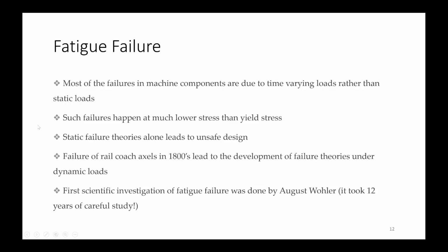Such failures happen at much lower stress than yield stress. So these can be below UTS and even below yield stress, depending on what stress amplitude you are taking and other factors such as the presence of cracks in the specimen. Static failure theories alone lead to unsafe design.